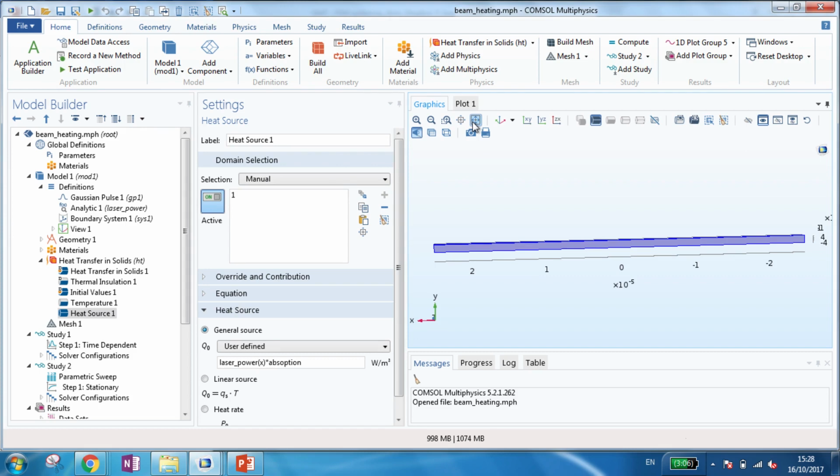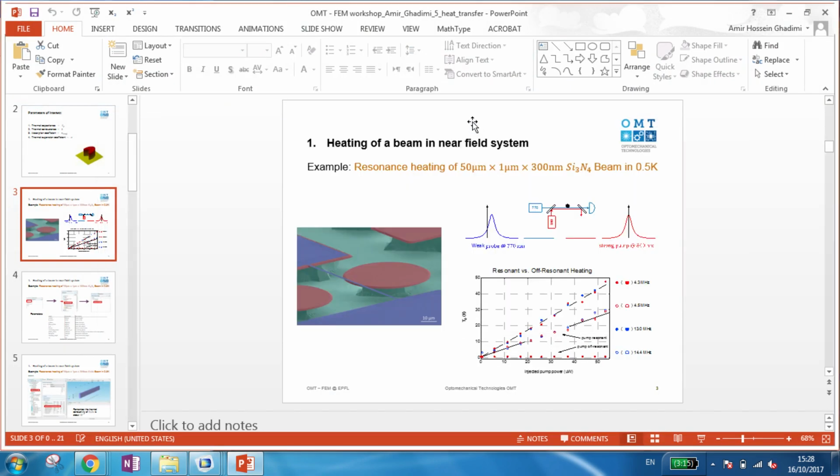So I want to do something which is weird. The thermal source is not at the boundary, which is usually the case for all this thermal transport, where the energy comes from a boundary and leaves. Here the heat, the basic heat element, comes from within. You have an optical light shining at the center, it forms a Gaussian spot, and a part of it will be absorbed. So to do that, first of all, I need to define a Gaussian function.